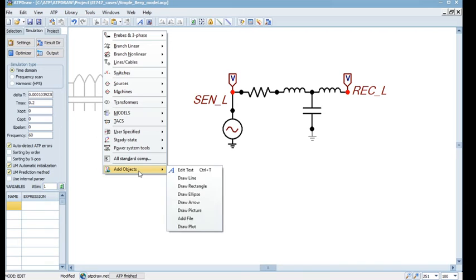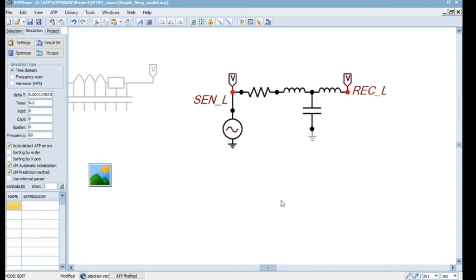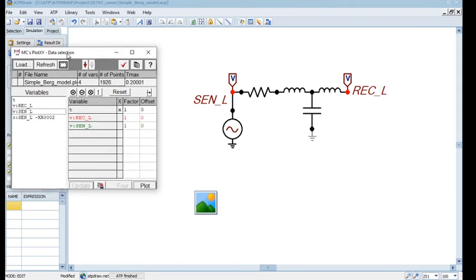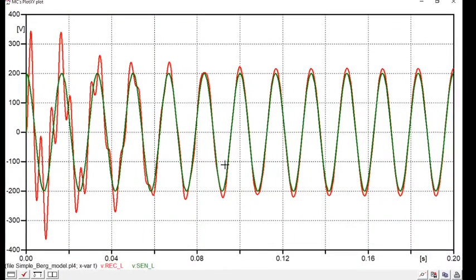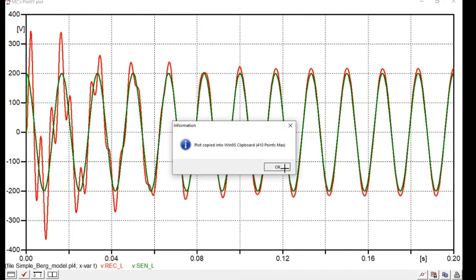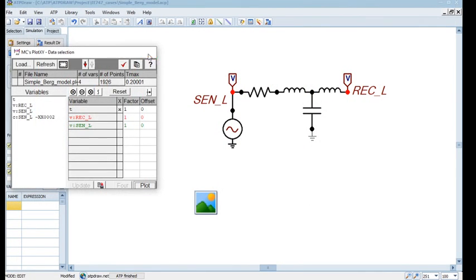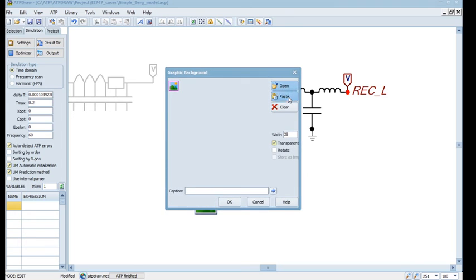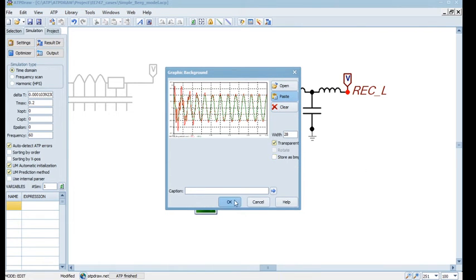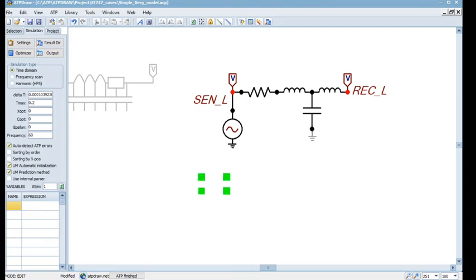So that's the idea. And if I want to place, let's say, a picture of the waveform, the results I got when I simulated, you can just save it as a picture here. Let me just open the result, click some results, plot, fine. And there is an option here, if you go lower, you have some save variables and plot copy option, fine. I'll just say copy, so it says okay, plots are copied, fine. So I can just double click and paste, in fact any diagram or any notes also, and if I say okay, it just gets generated.